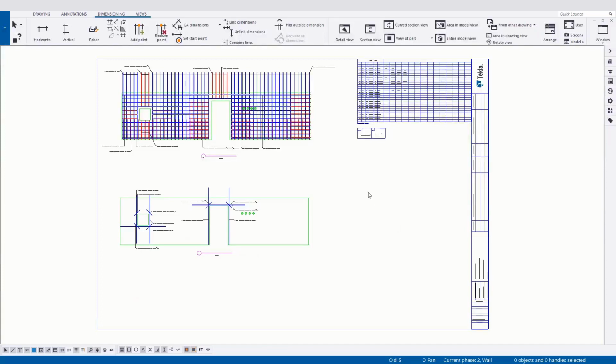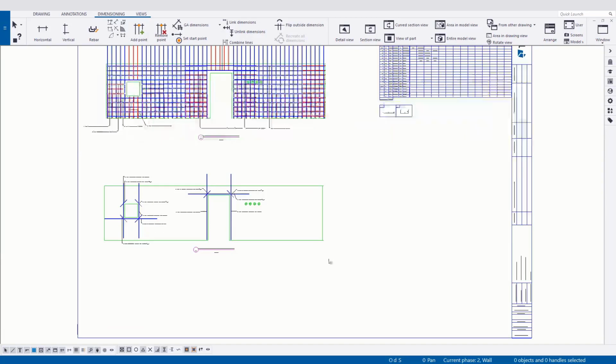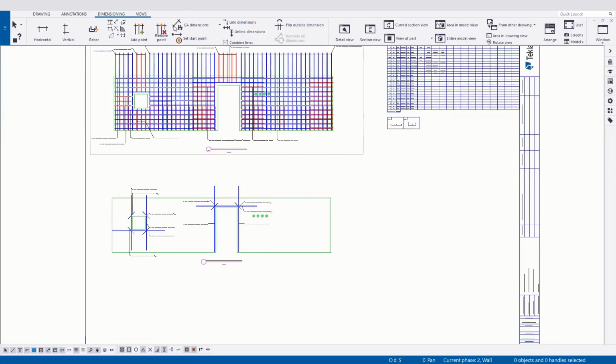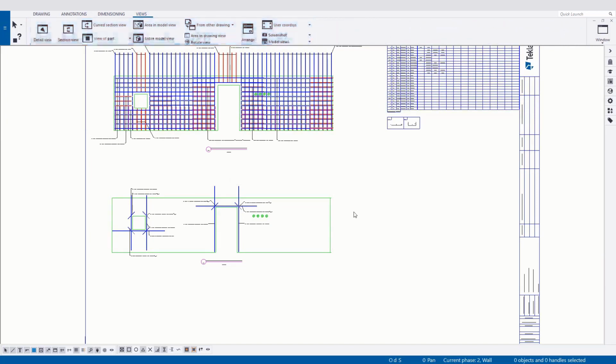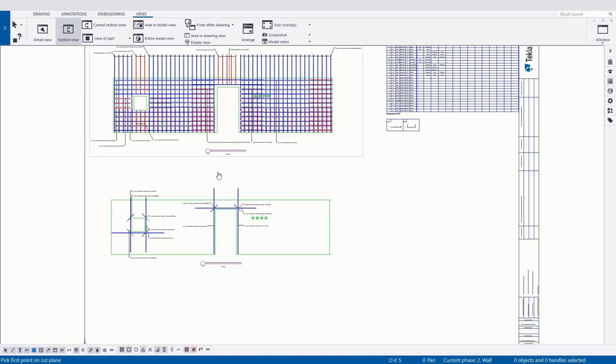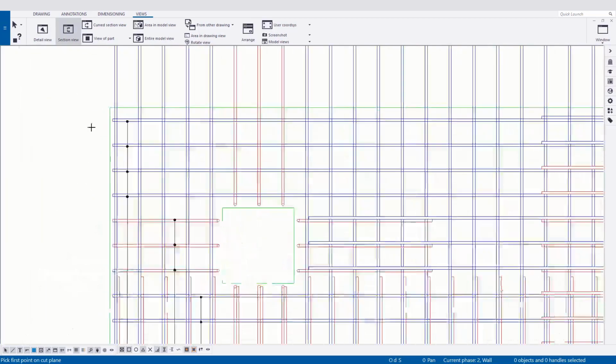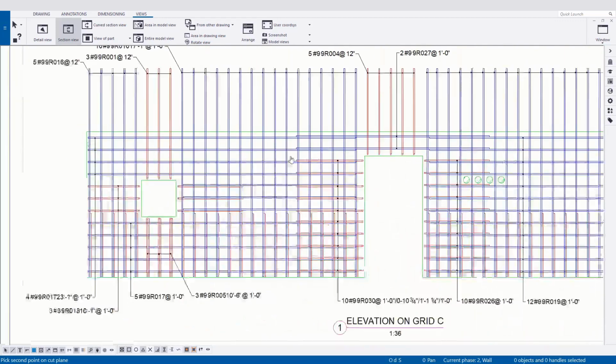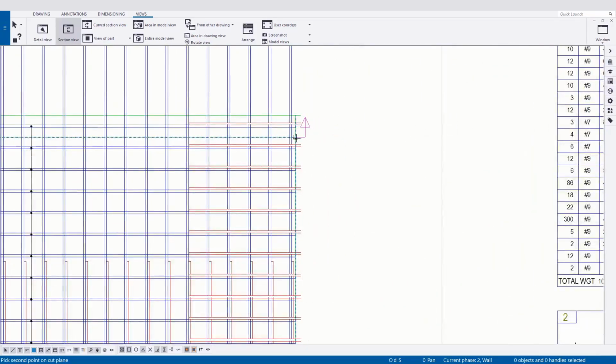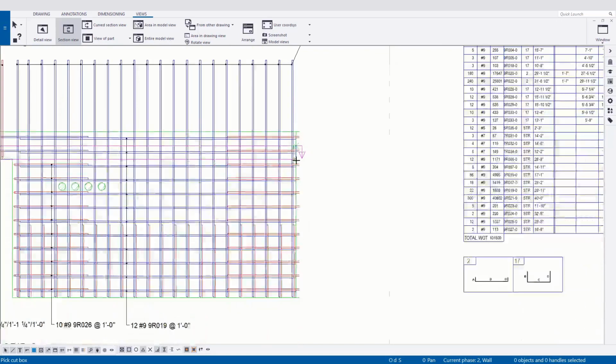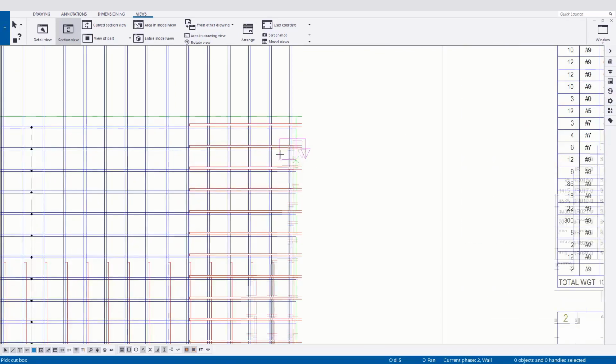Now, once you've taken a few minutes to update and clean up your annotation, you can still continue to modify the drawings however you need. One thing that we haven't touched on quite yet is making section or even detail views. Section cuts are pretty easy. You just choose the tool and then choose where to provide a cutting line, and we'll snap perpendicularly. Then we're going to pick the direction we're looking and how far down, estimation wise, using the graphic there.